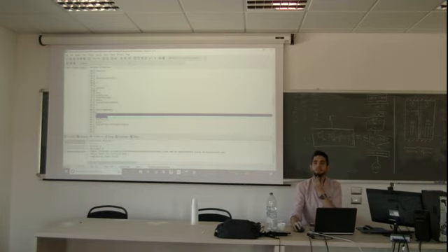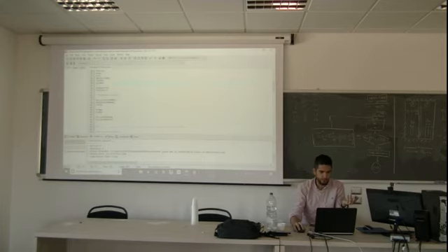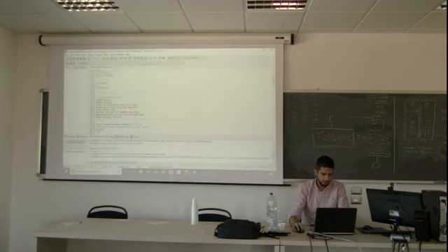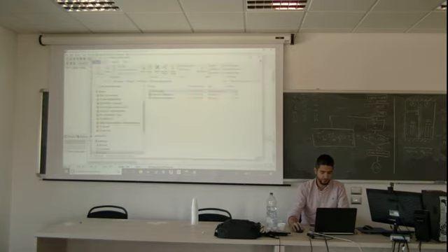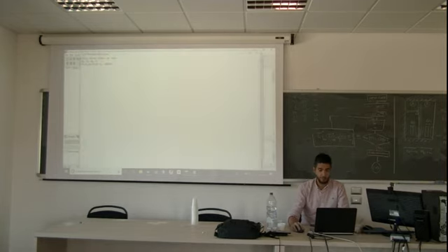Okay? Any question? No? Then we can play here, if instead of 500 we have, I don't know, 5,000, we can see the effect. You see, we have too many nodes now for this space. 12 seconds to run. You see, the temperature has changed a lot because there is 10 times more heat generation.